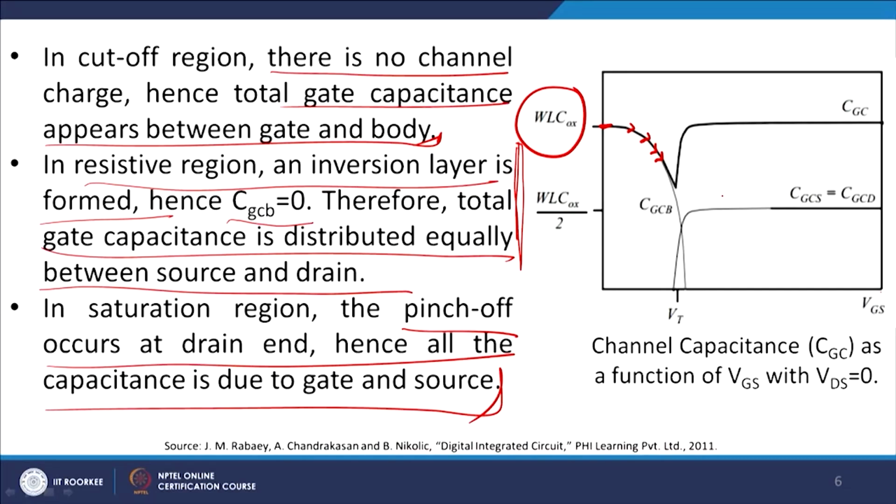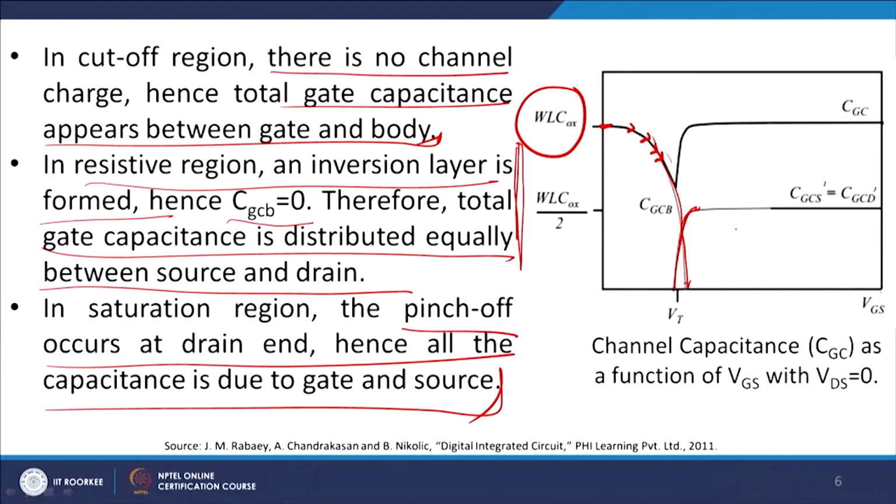If you look very carefully, the total charge we will see later on, but below Vt the contribution is gate to channel bulk, as I discussed with you, but it falls down, and it goes something like this, right, because the screening effect is there. Beyond Vt, gate to channel for source and gate to channel for drain, it looks something like this, it becomes larger and larger, right. But as the gate voltage becomes larger and almost fixed, I get that the gate to channel source contribution and drain contribution are equal, and therefore, you see it is given as WL by 2.